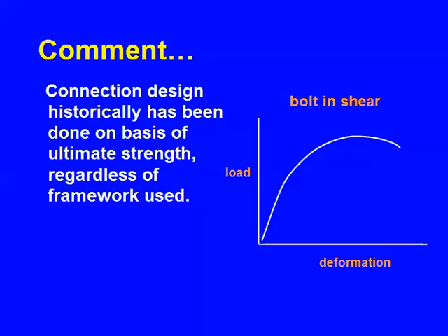There is no yield point. Don't try to give me a rule based on yield. That's what allowable stress design did at that point in the way the specification presented it. But behind that was always the ultimate shear strength knocked down by a suitable factor. So this is one illustration. Others apply equally. It was always done on the basis of ultimate strength, which makes it awfully convenient for me to deal with LRFD and for you to deal with either one of the two.